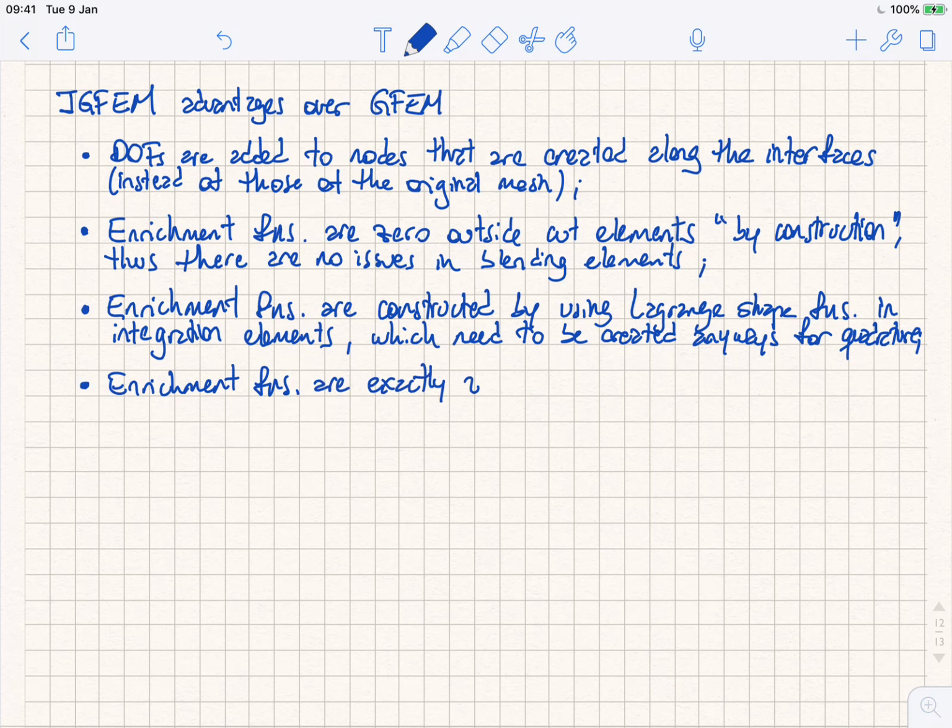So you preserve partition of unity at the nodes? You preserve the partition of unity at the nodes. In fact, what you preserve is the Kronecker delta property of the partition of unity. Remember that when we're adding an enriched formulation, for the most part, we are not going to preserve the partition of unity property. This we saw in PFEM, and it's also the case in GFEM.